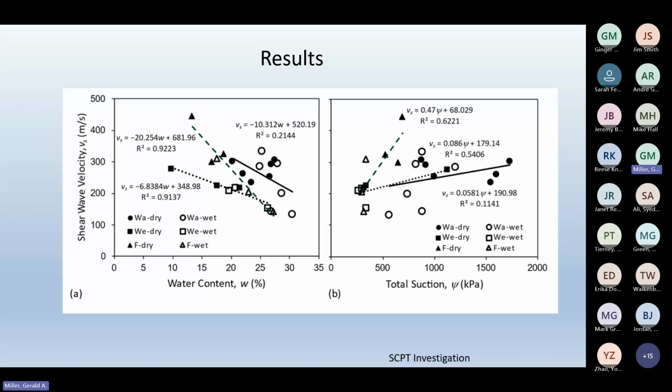I mean, even at a particular site, sometimes, like if you're in a fairly uniform material with depth and your moisture content's varying with depth, you might be able, on that given date, to plot moisture content versus shear wave velocity and see some rough correlation, assuming the material hasn't changed appreciably over depth.